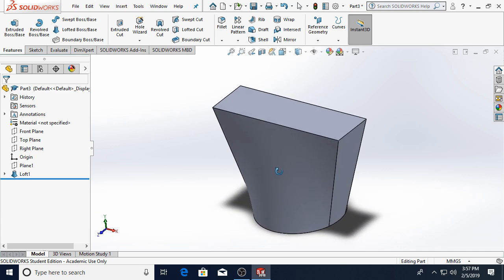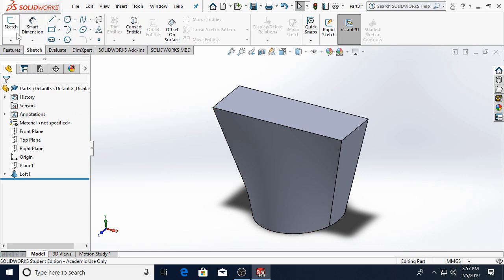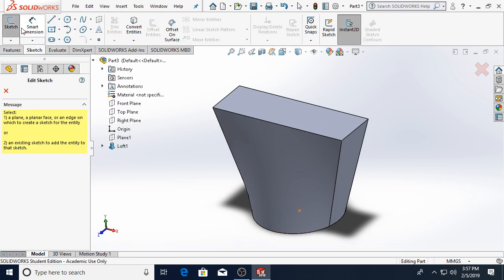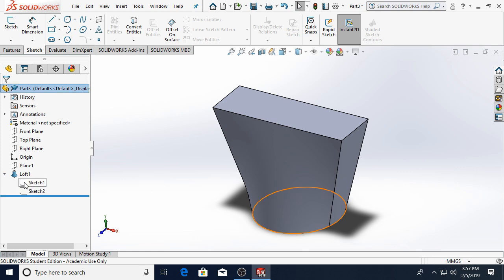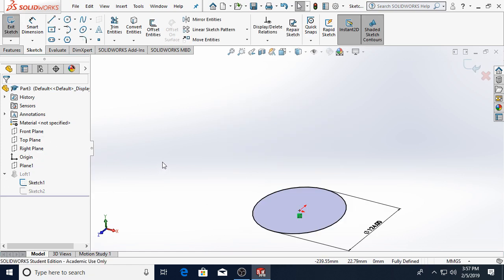It handled all the math to figure out how to transform one shape to the other automatically. Very convenient. Now, I could create two new sketches if I wanted to create a cut section in the middle that allowed for a 2 millimeter wall thickness, or I could actually go back and reference those two sketches again. Anytime that I want to reference a sketch instead of a feature, I just have to open it under the hierarchy.